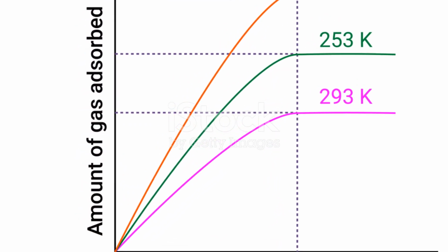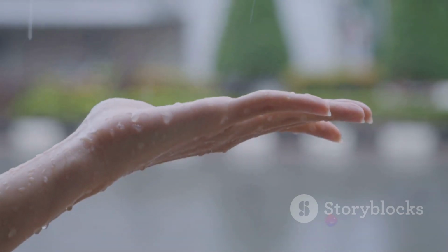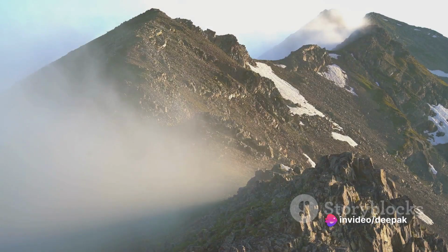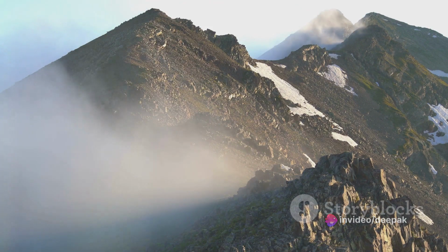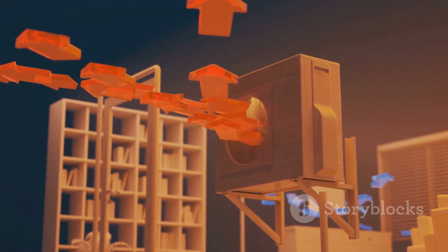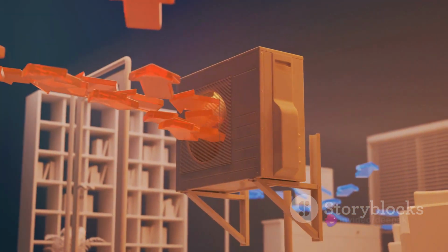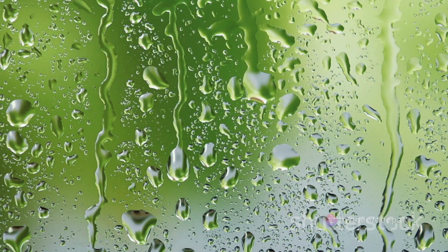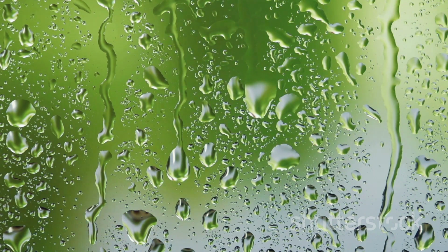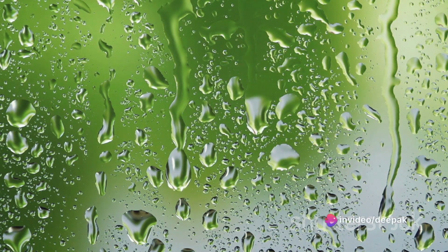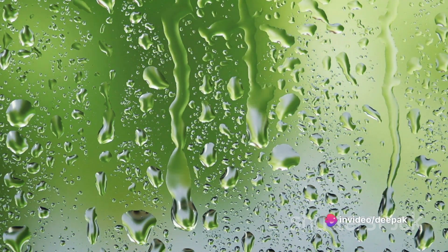The curved line on the far right is the saturation curve, which shows the maximum amount of moisture air can hold at a given temperature. Any point to the right of this line represents supersaturated air, a condition that usually leads to the formation of dew or frost. Other lines on the chart represent the wet bulb temperature and dew point temperature. The wet bulb temperature is the lowest temperature that can be achieved through evaporative cooling, while the dew point temperature is the temperature at which air becomes saturated when cooled without adding or removing moisture.